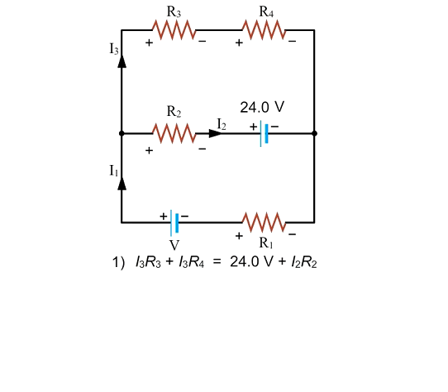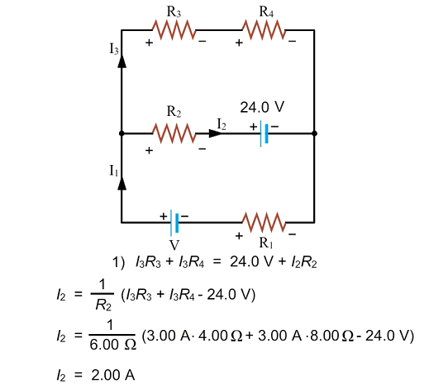Examining these equations and remembering that I sub 3 is given, we see that equation 1 will give us I sub 2 immediately. Solving this equation for I sub 2 and substituting in the known values gives us the positive answer, which tells us that the direction for I sub 2 in the figure is correct.